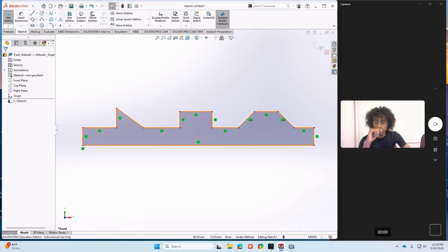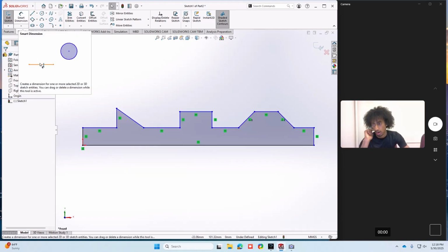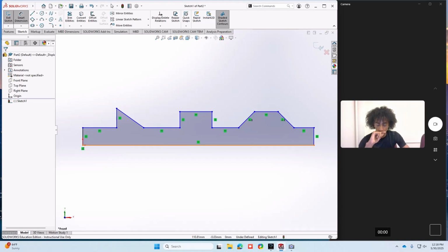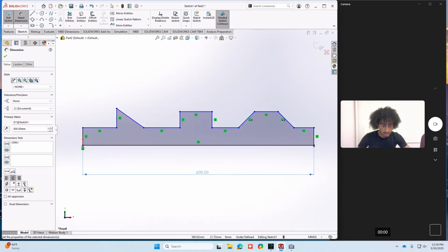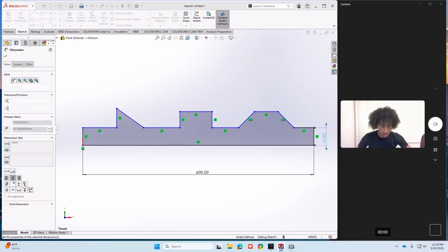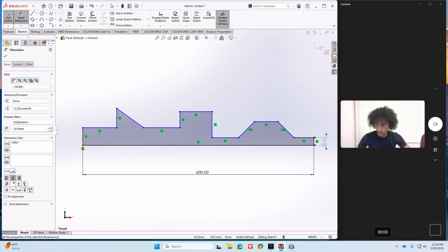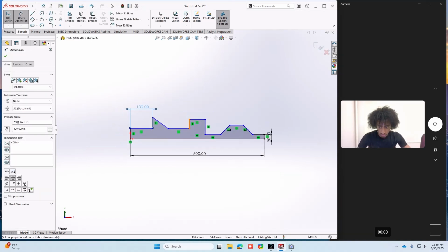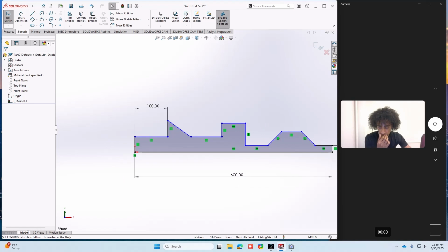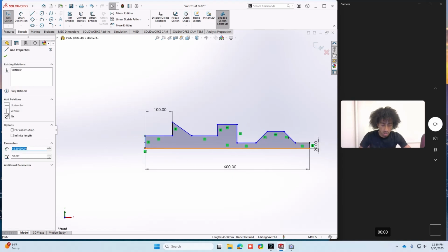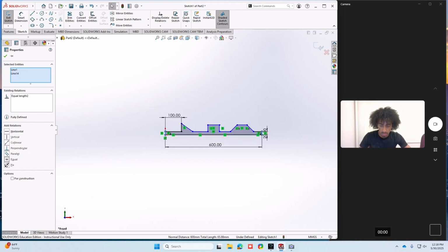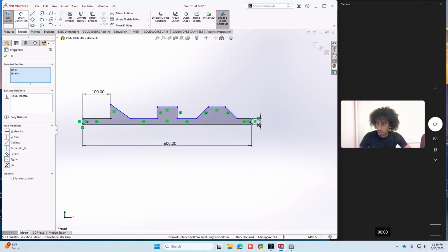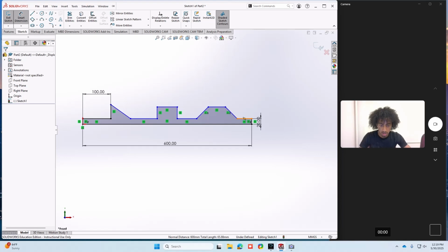One thing we got to worry about is the inside dimensions. We don't really have to care because, like I said, we're not going to add anything to it. The most important part is how long the piece will be, in the length, obviously. But other than that, it should be alright. This is 100. And also, okay, perfect. What you want to do is make sure you have your side parts. You can hold shift to make them equal. So they're both 2. This is 100. Oh, and also I forgot to mention the distance between these two should be 30.